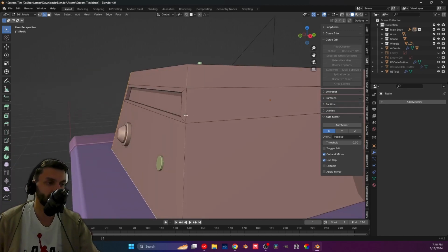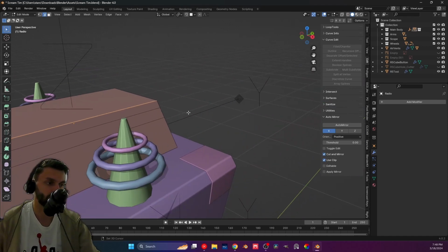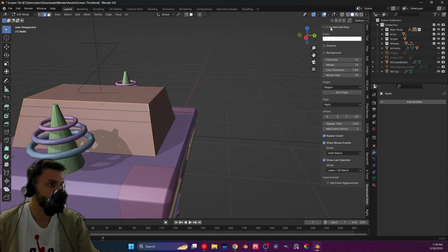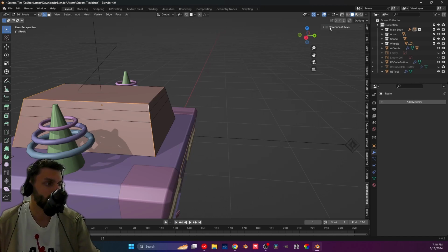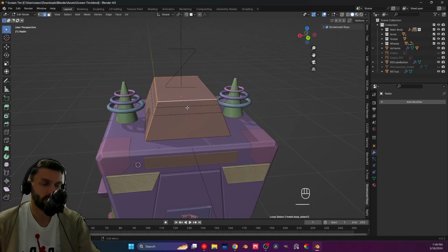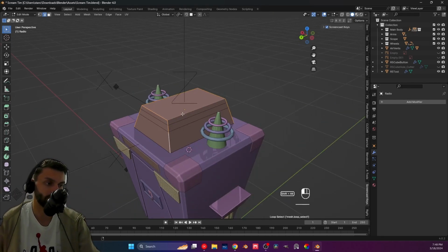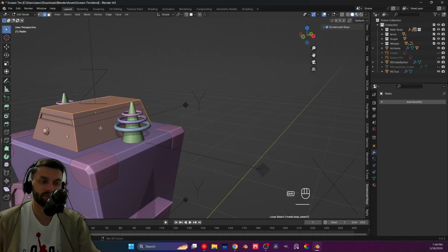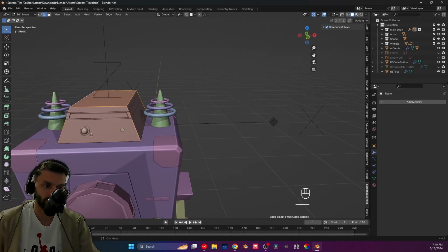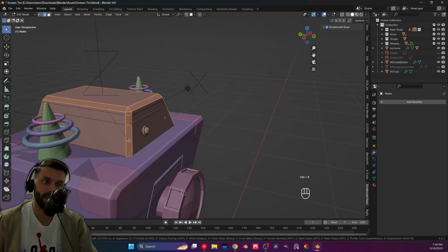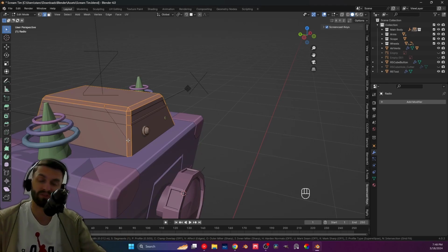So again, it's something I did talk in my beginner tutorial a little more in depth on how to select these edges. But basically what you do is actually press, and actually let me get a screencast on just for you to see exactly what I'm pressing and when I'm pressing it. But you press Alt, Shift, left click, and you are able to select everything at once, right? So for example, I want all these and without this to actually be selected, and I want to be able to bevel them, which now I'm able to bevel them separate from everything else.